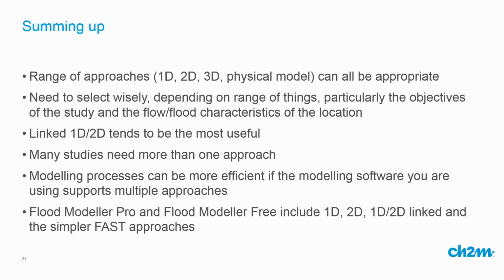So I've talked about a range of approaches. I've talked about 1D and 2D and linked 1D, 2D. There are other approaches where you can model the system in 3D, so that means there's a different water level at different elevations at a point, and you can use physical models to represent some of the system. All of these approaches can be appropriate, although it's 1D, 2D and linked 1D, 2D that are the approaches most used. 3D may be appropriate for the design or assessment of some very special structures in the channel, as could physical modelling, although neither of those last two are used very much in flood risk management.